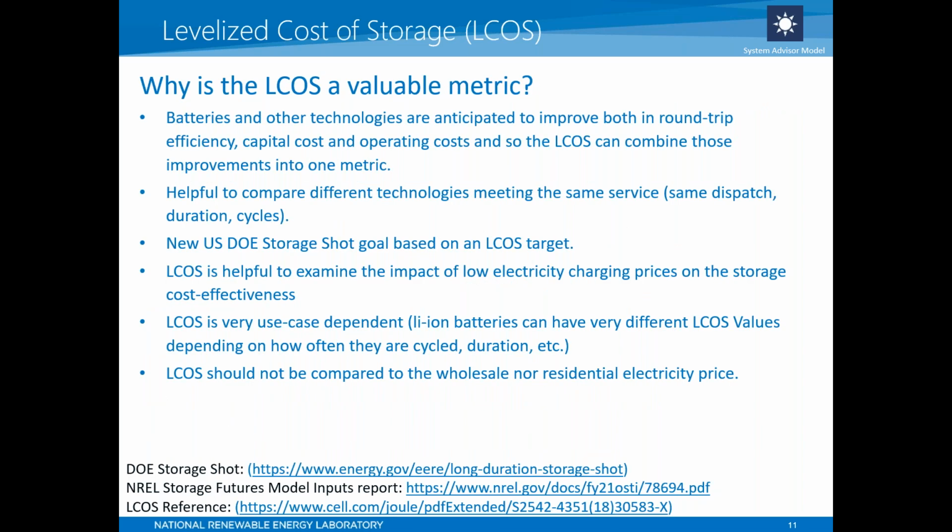So why is the LCOS a valuable metric? As time goes on, batteries and other storage technologies are anticipating improvements in round trip efficiency and in cost considerations, both capital and operating costs. And so the LCOS can capture how the efficiencies and costs improve for batteries as time goes on.